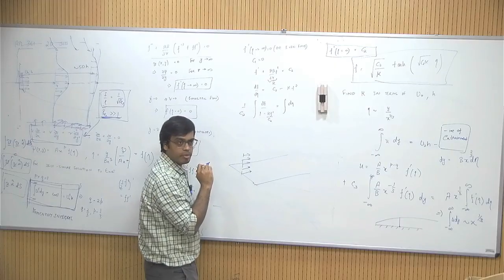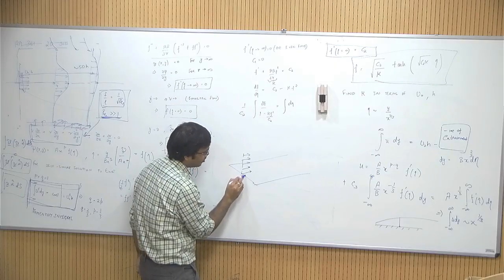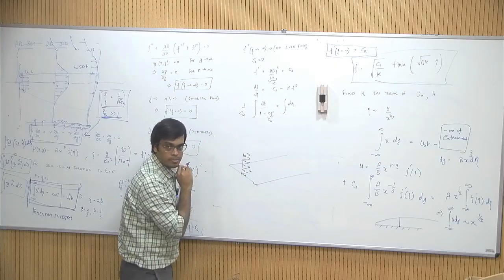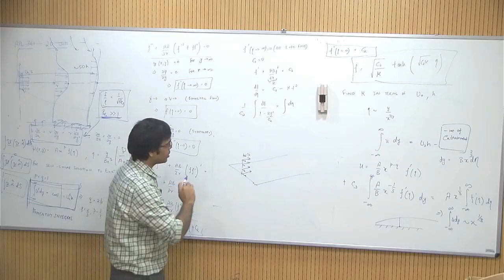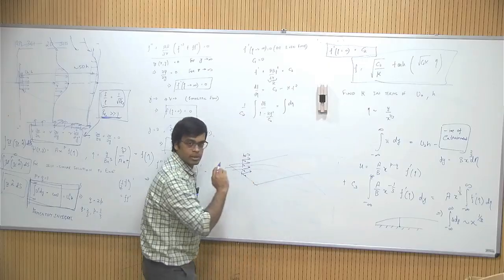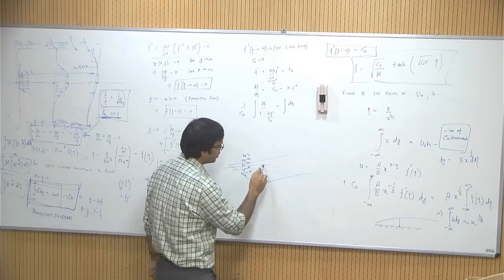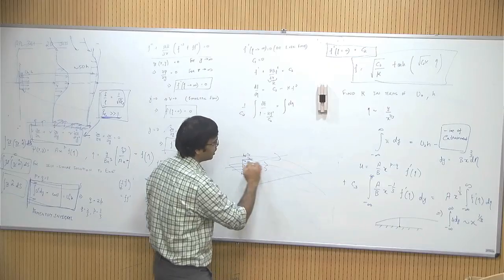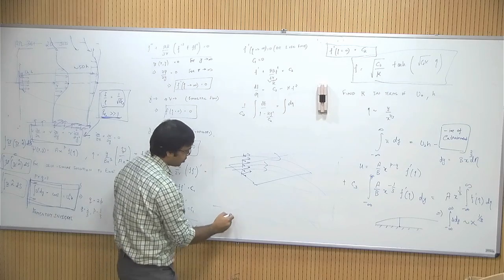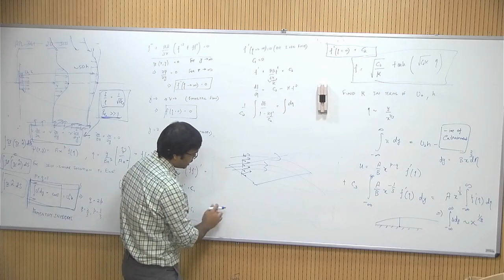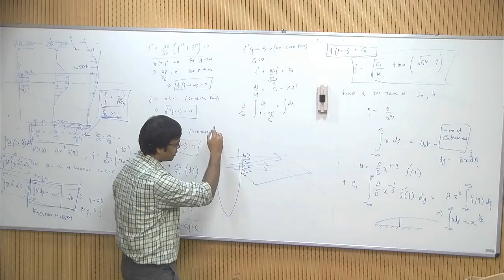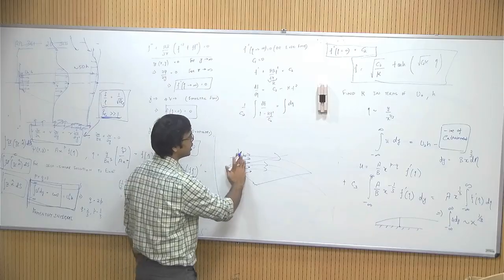In 3D boundary layers what you do is you add a component which is spanwise as well. If you looked at the steady flow streamlines, they will probably be going something like this. Why are 3D boundary layers important? Because if you look at the fuselage of the airplanes, let's say you're looking at the top view, you have this as the fuselage and this is where the wings start.